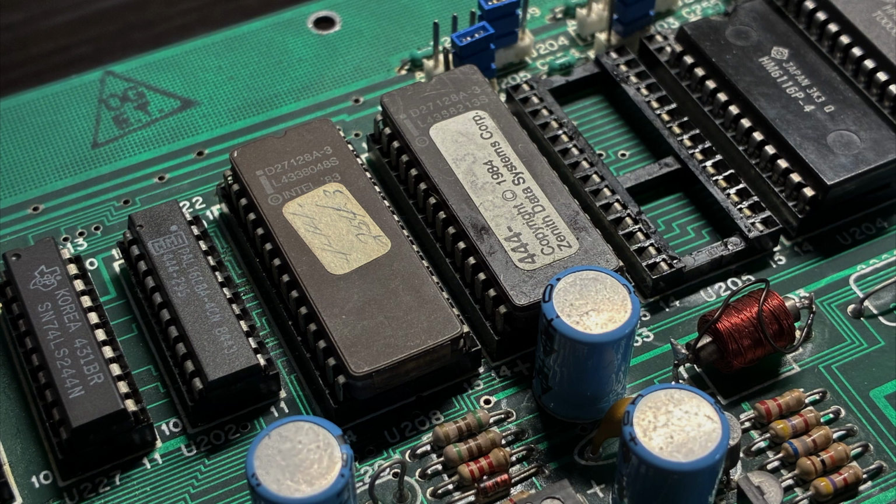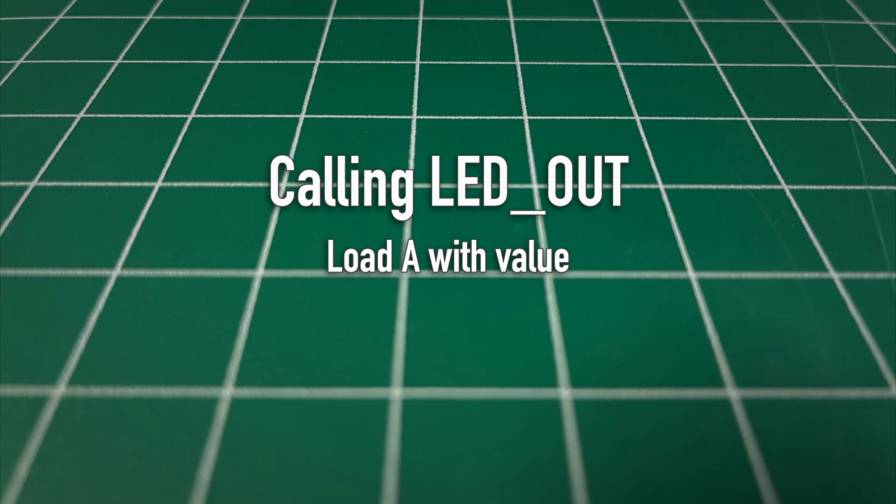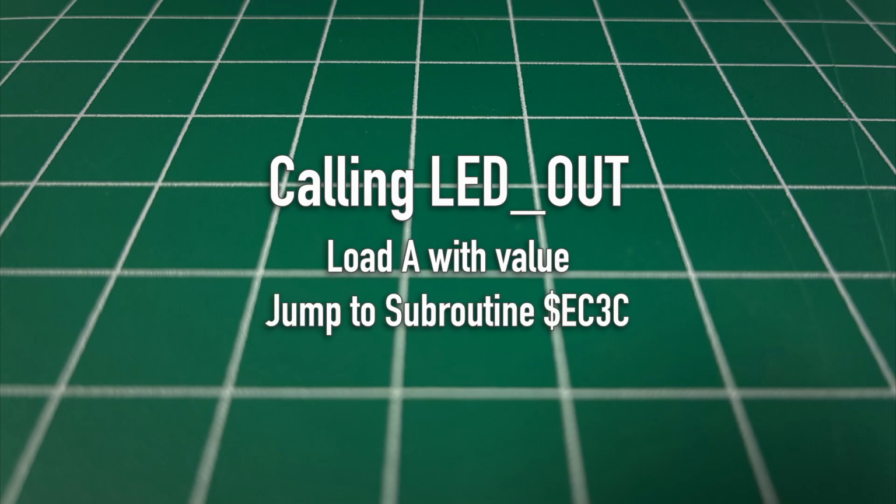Let's borrow a ROM routine to help us out. It doesn't have a real name in the official ROM disassembly, but I call it LED out. It lives at address EC3C. To use it, we load a number into the A accumulator and then JSR to the LED out routine at EC3C. Let's give it a try with hexadecimal 00.